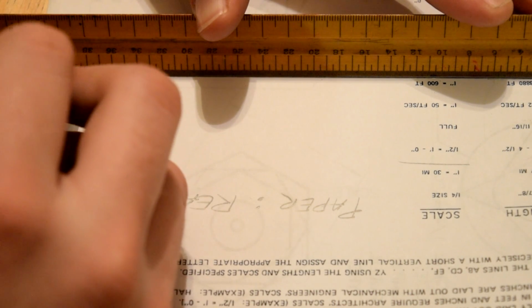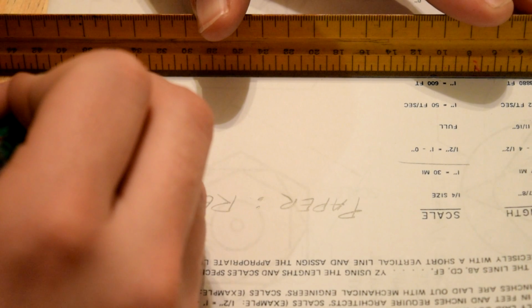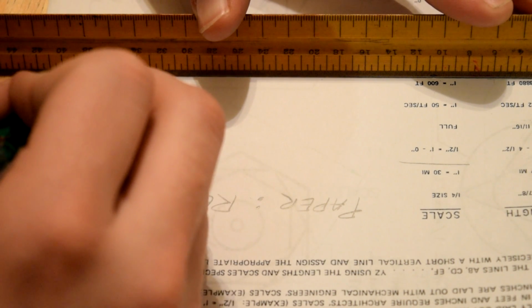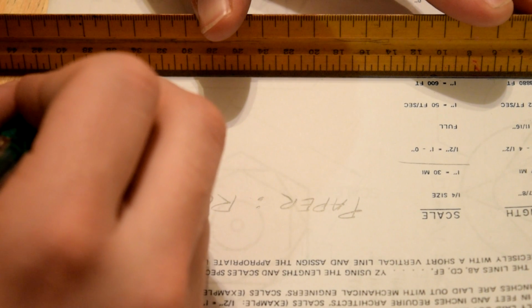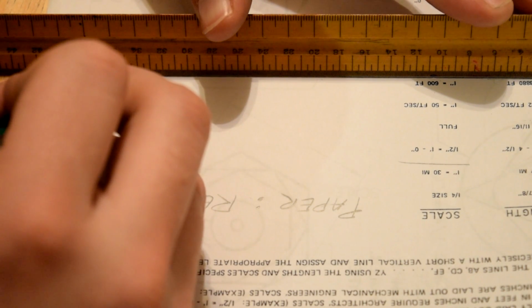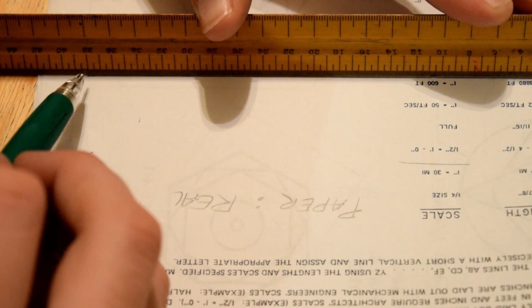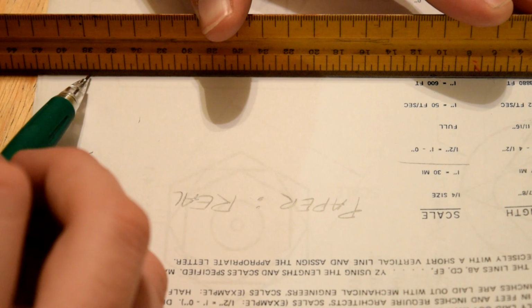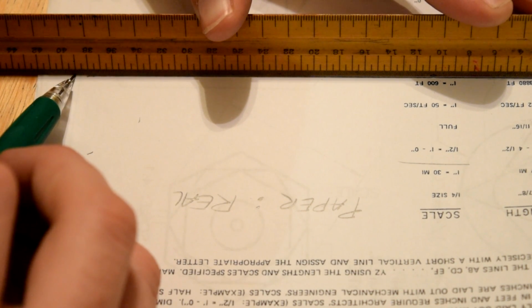Since I'm not quite going to 39, I'm going to 3,880, to keep myself 20 feet shy of that next 100 foot mark, I'm going to go out 4/5 of the way there. So I can use the marks on the paper to carry out the remaining 4/5 of the distance between 38 and 39.